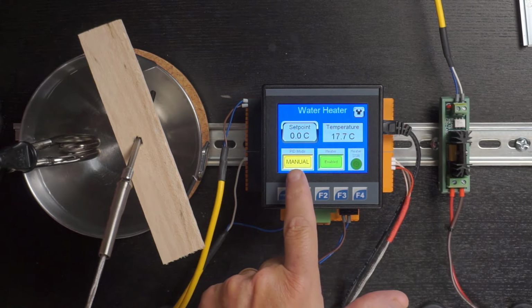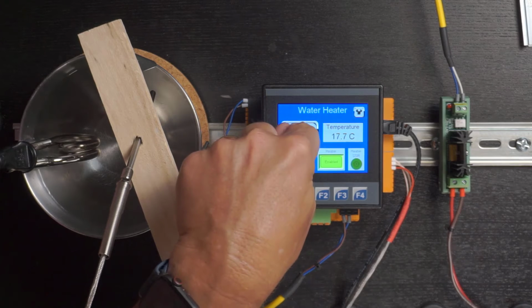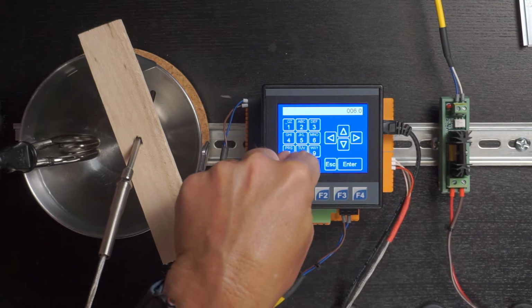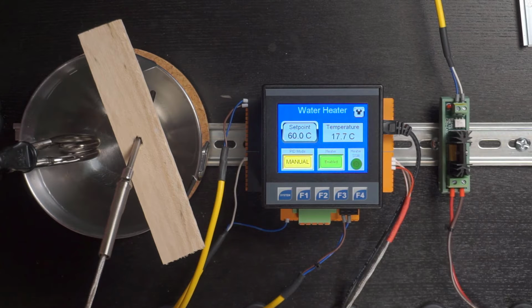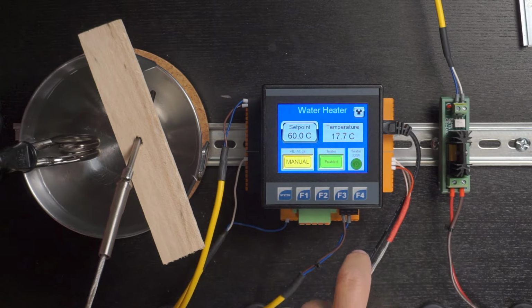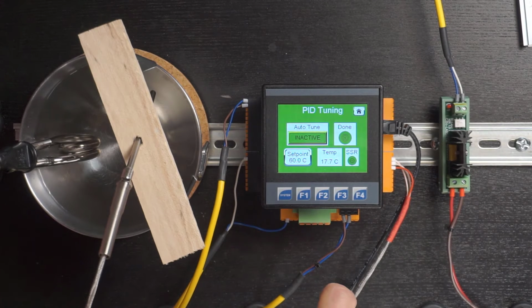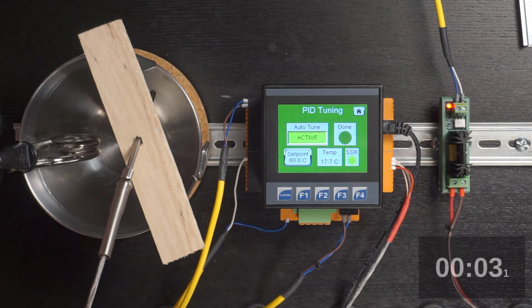All right, I'm in manual mode. You can certainly tune from manual mode. That's not a problem. My heater's enabled. I'm going to go ahead and set my set point for tuning at 60 Celsius. Currently, my water before heating is at 17 or 18 degrees Celsius. Let's go to my tuning screen, and I should be able to just kick off the tune here. There we go. You'll notice my SSR is on. So what we are executing here is a Ziegler-Nichols tuning experiment being automatically run by the OCS.